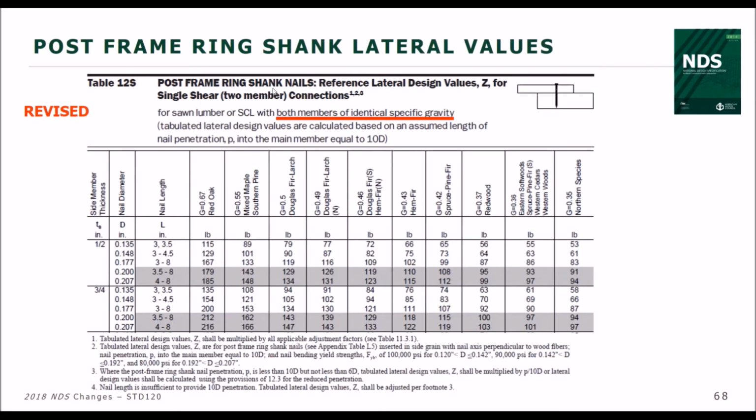Now we get to the post frame ring shank nail design values. And so we've revised those slightly because of a change in the bending yield strength, or better information, I guess, about the bending yield strength of those post frame ring shank nails. So you'll see just a slight decrease in the values here for post frame ring shank nails because of that.